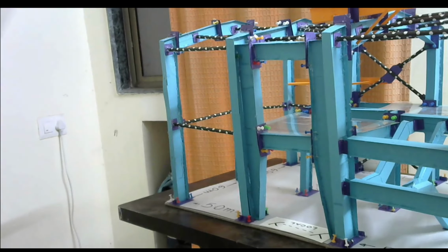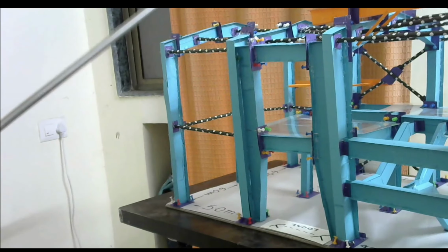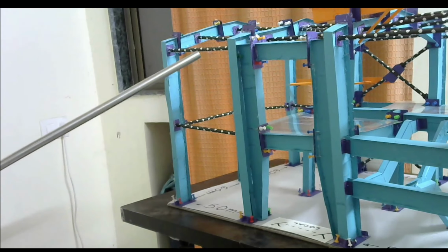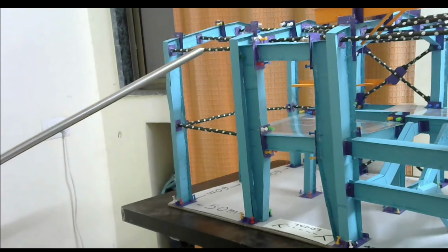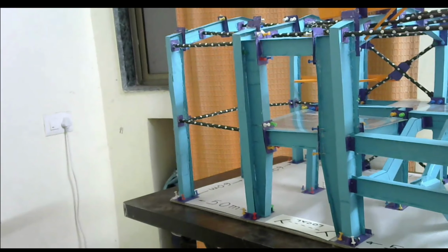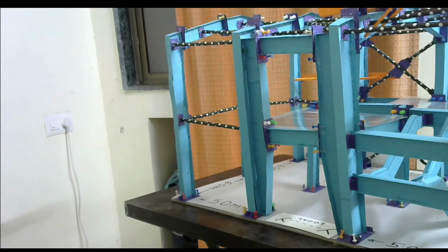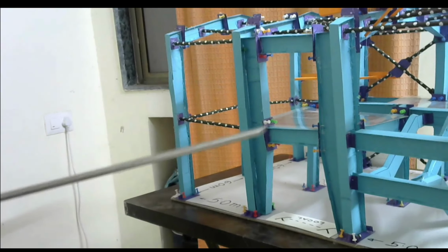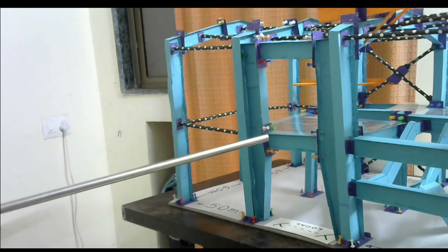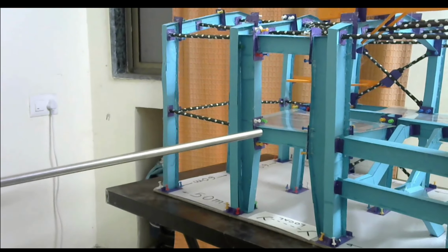See, actually, a portal frame is a sway frame. So sometimes a second-order analysis is required, to check whether we can consider a portal frame as providing adequate lateral strength to a column so that we can take its effective length as 1. IS code does not elaborate much on this, but there is some elaboration in the AISC code.